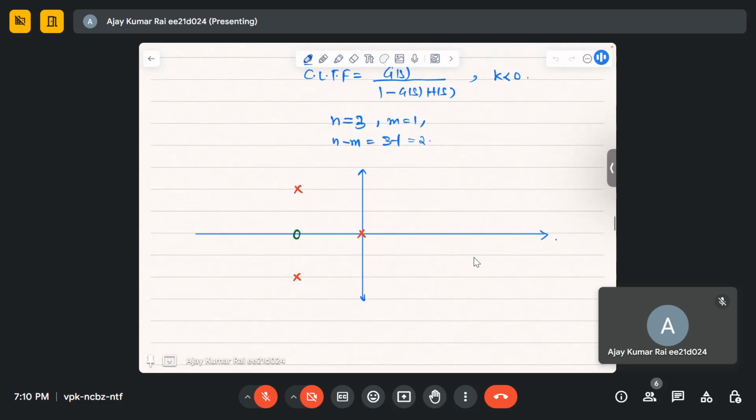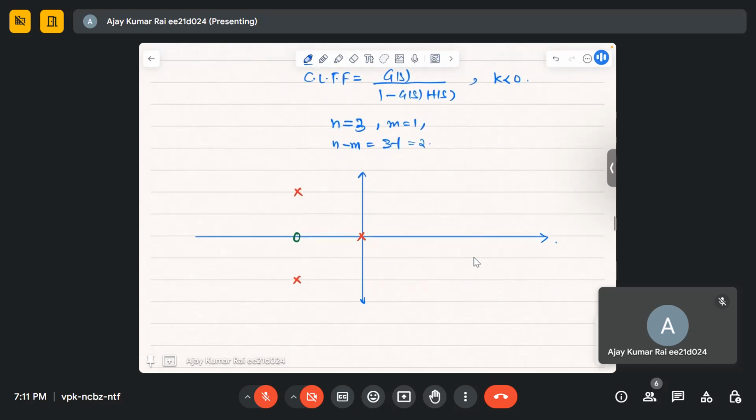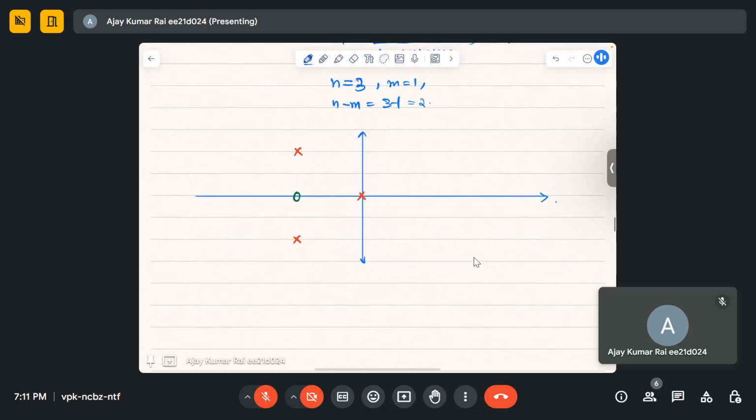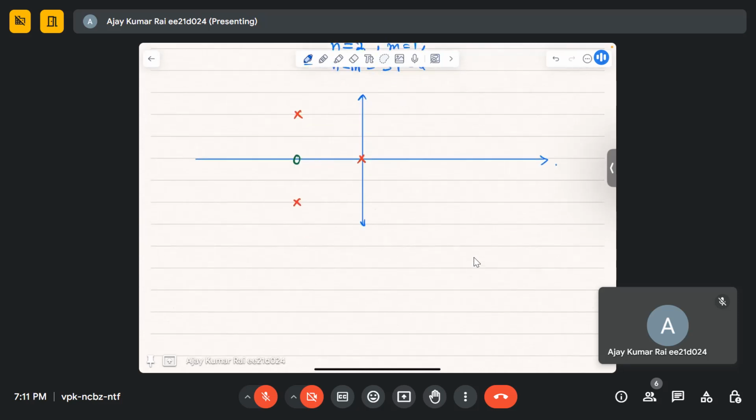So the root locus will exist here. The second step was plotting the root locus on the real axis. We know the root locus will exist here, because if you take a test point here and look to the right, you'll have one pole. For the other two regions, the root locus will not exist. The step 3 was the breakaway and break-in points.